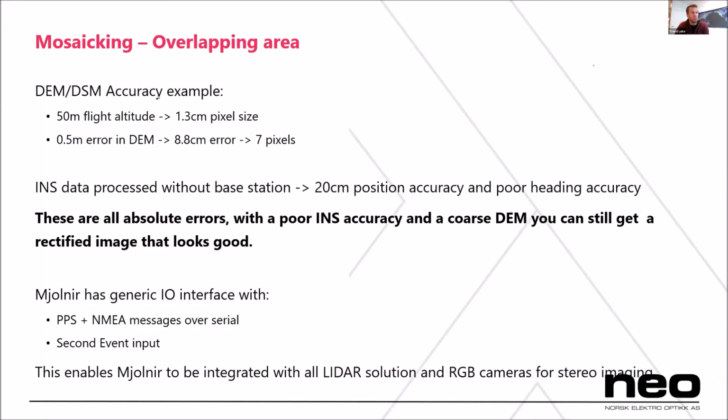Yeah, this is the example I mentioned, that if you're flying at 50 meters, our pixel size is 1.3 centimeters. And if you have a half a meter error, you are getting 7 pixels in the elevation model. You're getting 7 pixel error in the overlapping region. So when you're talking about UAV systems and boresights, we are usually talking about millimeters in boresight accuracies rather than centimeters.